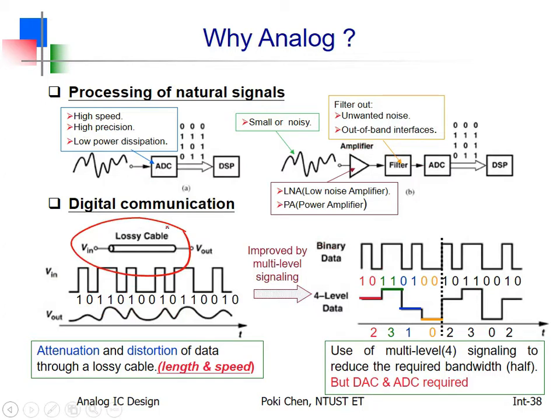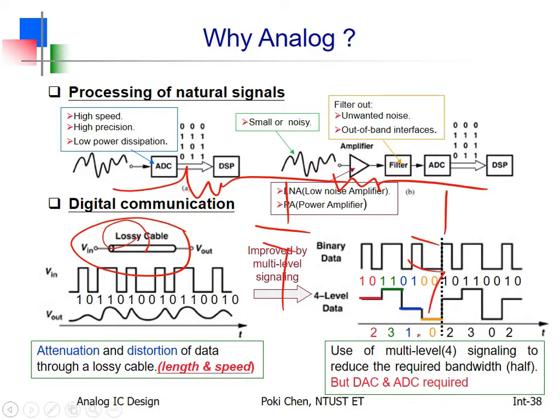Allow me to show you a very good example. How can you transmit the 1s and 0s from here to there? We need wires, cables, everything. Metal, nice. But again, nothing is perfect. Even if you use any kind of very good metal line, it is still lossy. It means it has parasitics, R and C and R and C. You have a lot of R and C parasitics.